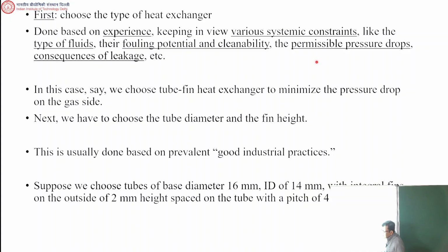Now, this choice comes partially from experience and from industrial practice. If you are an engineer working in an industry, you know that for this sort of application, a tube fin heat exchanger works out well. There are many instances of people using it. Also, a tube fin heat exchanger is good for gas to liquid heat transfer.